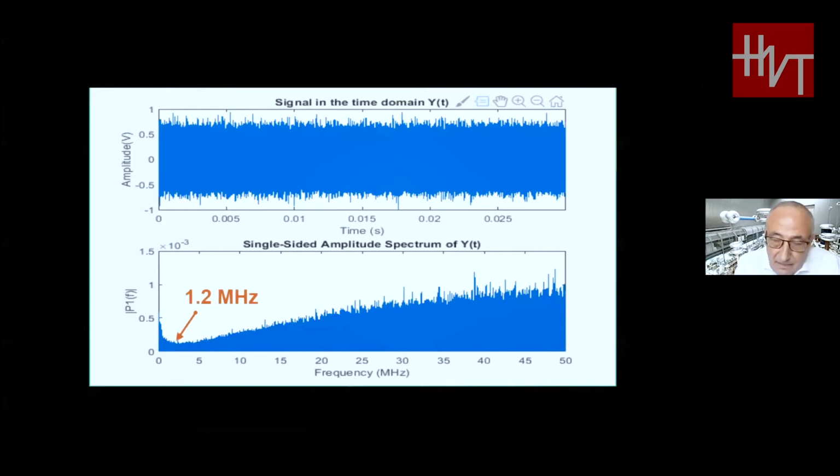To measure the noise, you remove this high frequency sensor and place it close to this conductor, in order to acquire signals in the environment, but not exactly the signal through the conductor, which is probably the PD signals.